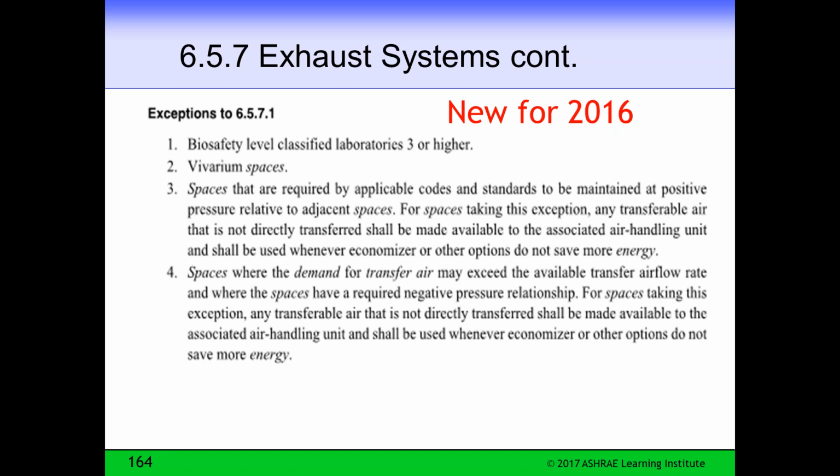Biosafety level classification 3 or higher, vivarium spaces, spaces that are required by applicable codes and standards to be maintained at positive pressure relative to adjacent spaces. For spaces taking this exception, any transferable air that is not directly transferred shall be made available to the associated air handling unit and shall be used whenever economizers or other options may exceed the available transfer rate.